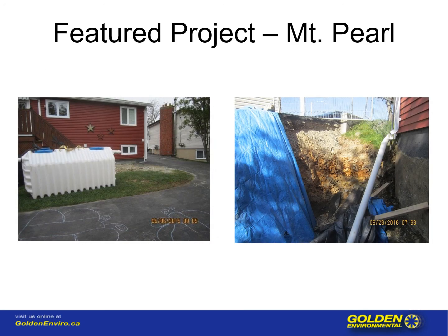The photo on the left-hand side is from the back of the house. The driveway on the right-hand side of the house would have to have been taken up if the home was to be underpinned and dig and haul chosen as the remedial effort. We saved that driveway and any potential damage to that neighbor's home. You also see a tank that is used for mixing. We bring in the amendment in concentrated levels and then mix it as we do the injections.